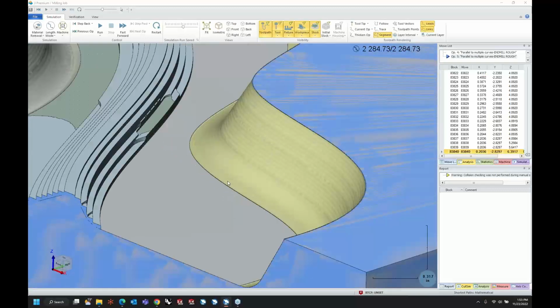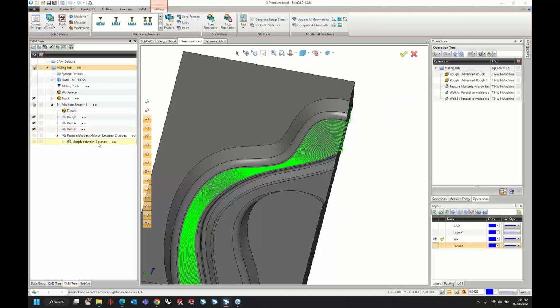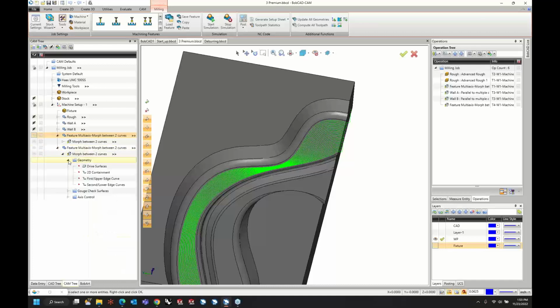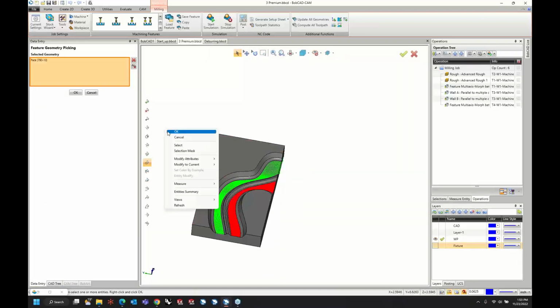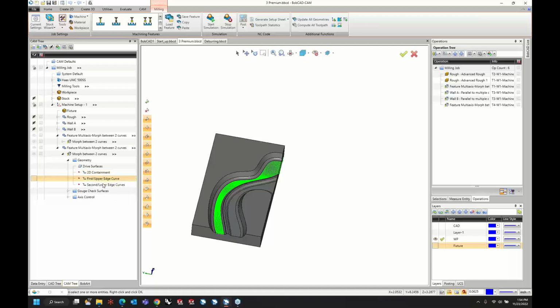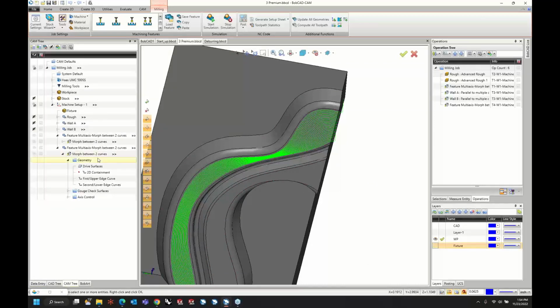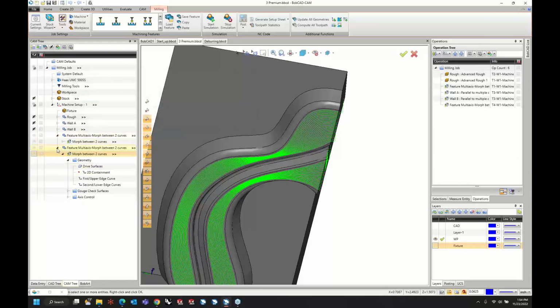And if there's a little step there, what I can do is expand the parallel to multiple curves. Let's go ahead and copy this, paste it back in, and then the other side is going to be the other one. So we'll select our drive curve. Then we'll go in and set our first upper edge curve, and it doesn't matter which one you do, you just want to pick both your edges. And then we'll go ahead and compute. And I'll call this floor A and floor B.